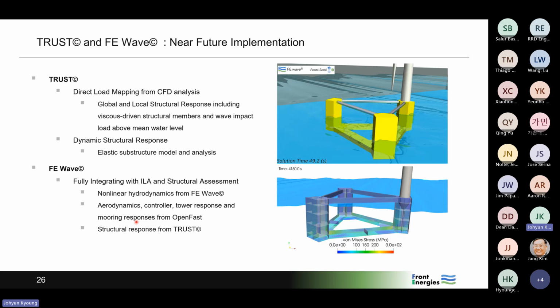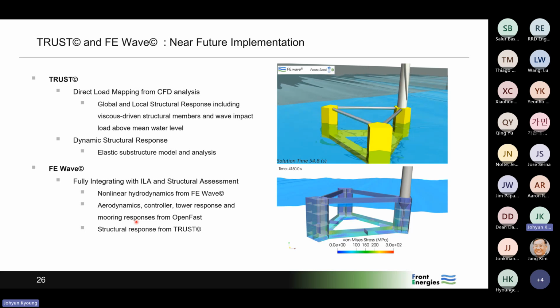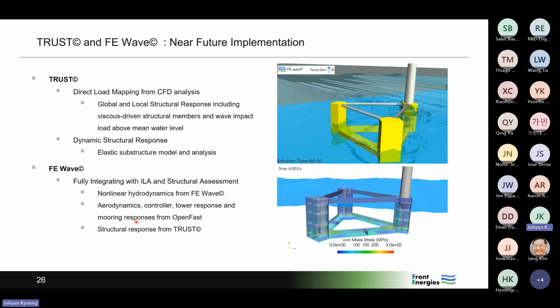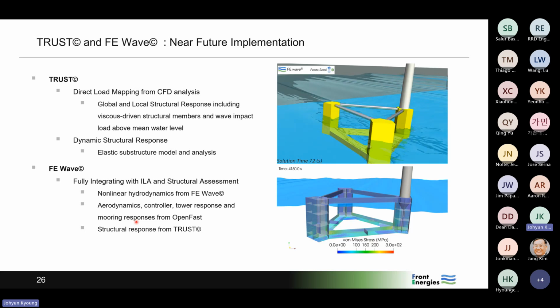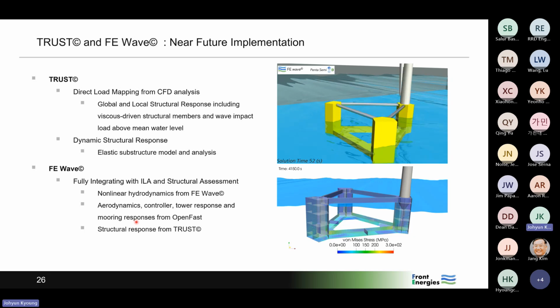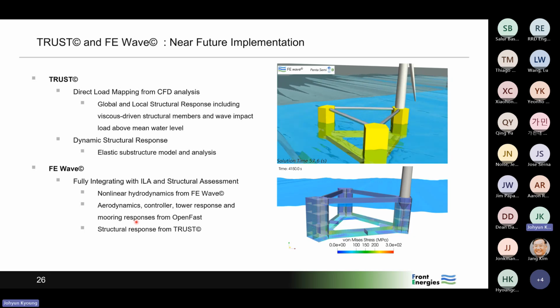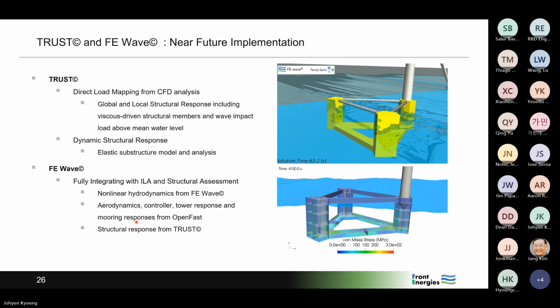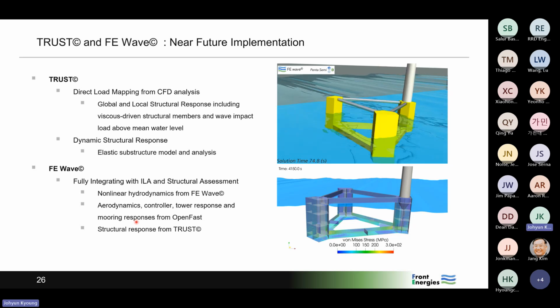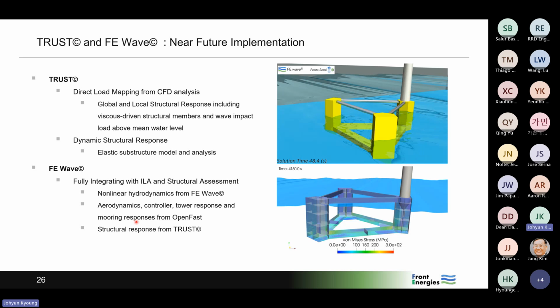Here it's clear, because you are calculating the motion and everything will be perfectly balanced. But when you use OpenFAST, then you load your finite element model with both the pressures and the motion, and this motion comes from OpenFAST. Yes, but there might be a misbalance of the inertia and the pressure loading.